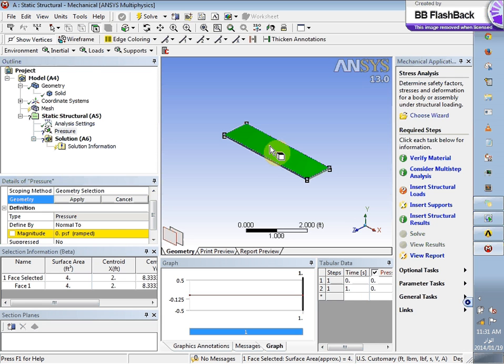This means it's selected, but it is saying in fact where you clicked below this point there were two surfaces available. One was the top face and other behind it is the bottom face. In which face am I interested? So now see, if I move my mouse on this one, you notice the rectangle there which will appear. On the top one, the top rectangle appears. When I select the bottom, the rectangle moves down. So you can now select whichever face you were interested in. So we in fact never needed to rotate it anymore. You can select the face directly from here.